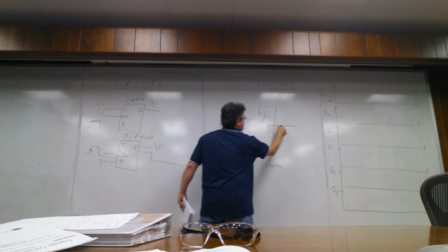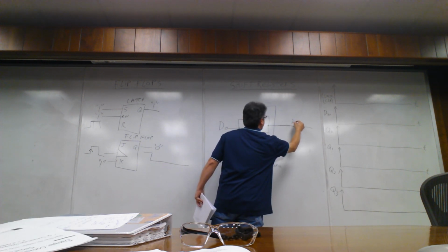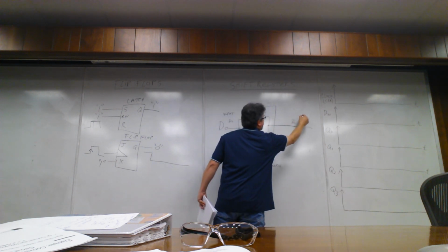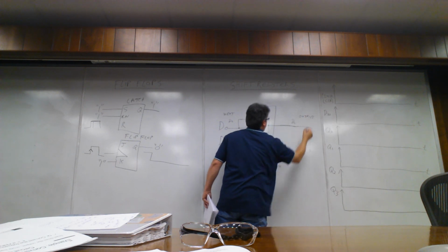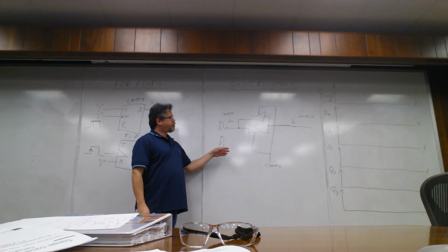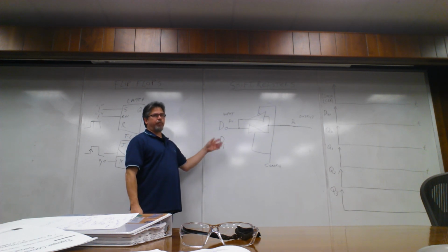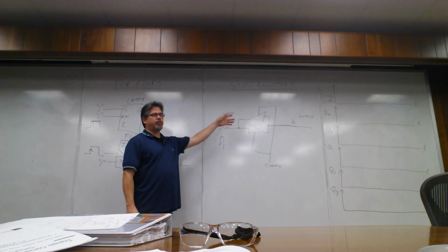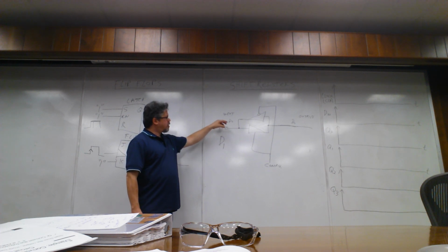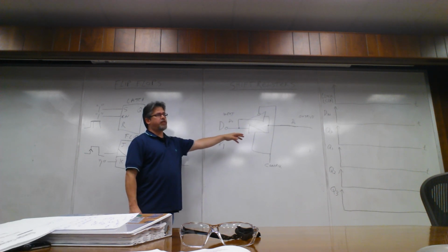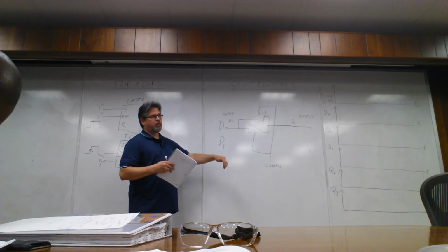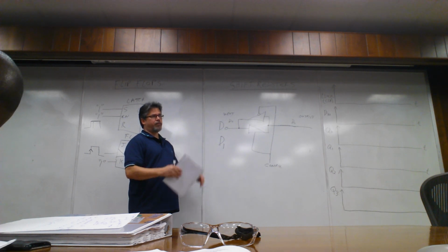And let's say this is the data bus here, this is D0, and this is D0 out here. This might be input, and this is output. What happens is, they might do a read operation. They want to read something in from an I/O device, which could be a sensor. Or the micro might want to go in the other direction, to write something out to memory. You don't want data going in two directions at the same time, because it causes bus contention. They contend for the same bus.